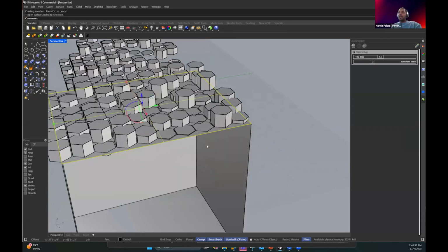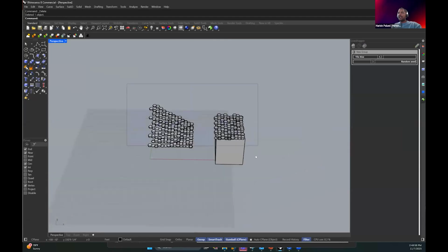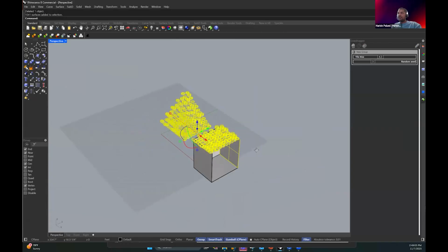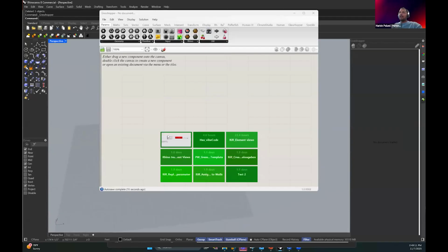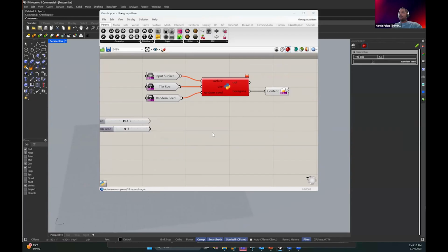But you can see you have a functional script already that just creates something in less than 15 minutes. You have the whole process. So this is how you would create a script in Grasshopper and add a bunch of inputs and outputs. It's all case sensitive. Make sure you get your inputs and outputs right. This would solve most of the issues.